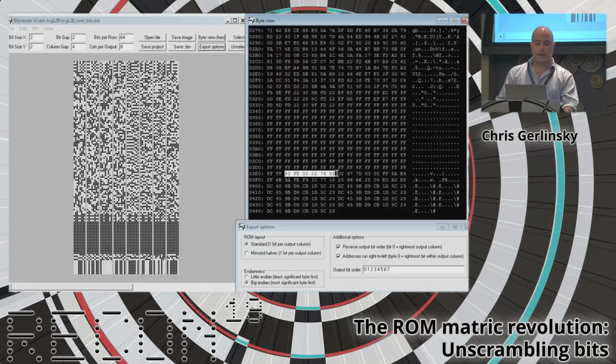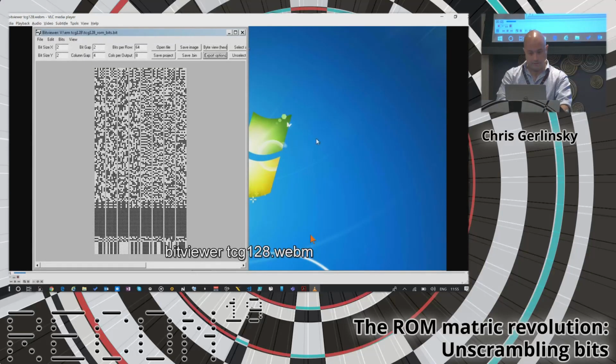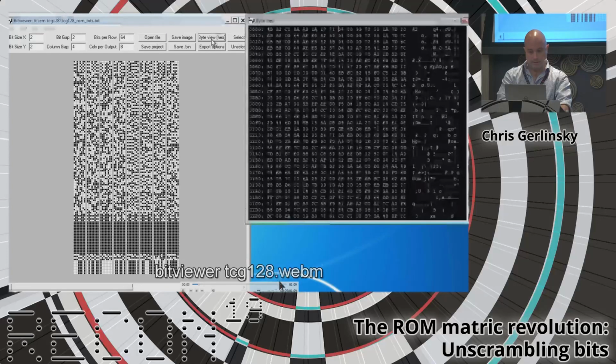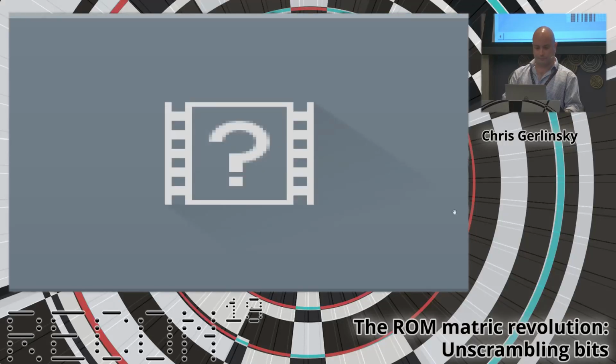And then after doing that, the next thing that I'm able to notice is there is an 8-byte sequence that appears to be plain text. That was a valid 8051 code. There was an infinite loop there, which is a pretty common thing to see at the end of code blocks. The ADFE is an infinite loop, followed by some long jumps. There's sort of a vector area. So there's 8 bytes that turned out in plain text, but the rest of it still isn't valid code at this point in this chip.